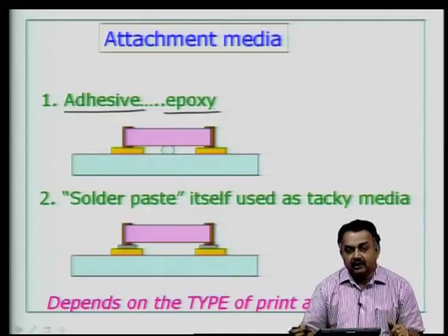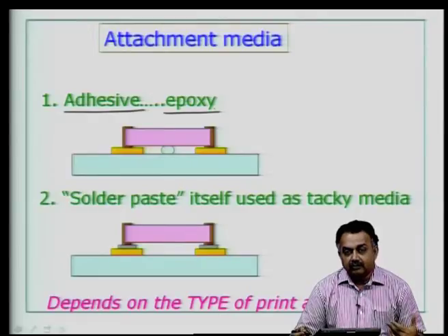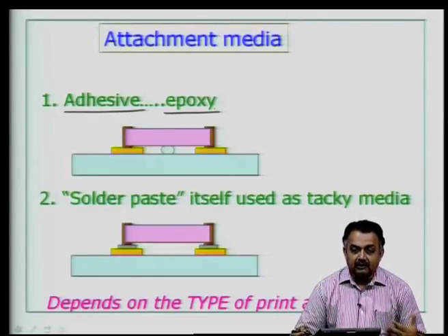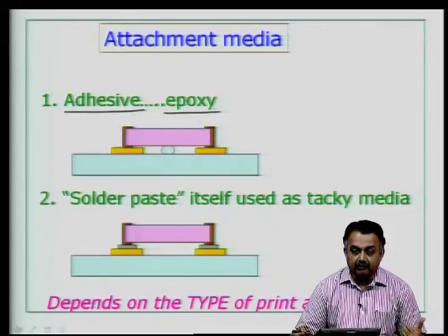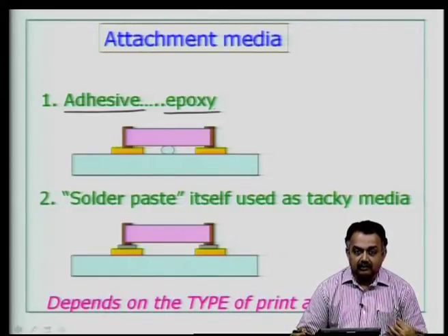I have been mentioning and talking about epoxy in this course for a long time, and you will now understand that epoxy has various applications in packaging. Affordability is one important criterion for choosing epoxy, because there may be other adhesives, but we use epoxy based materials for various applications like chip on board encapsulant, a flip chip underfill process, epoxy in solder mask applications, conductive adhesives, or simply a non-conductive glue and so on.